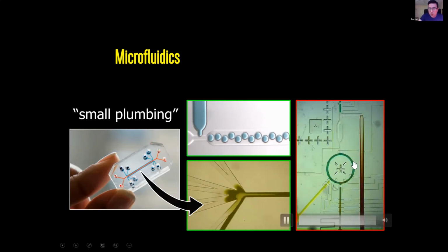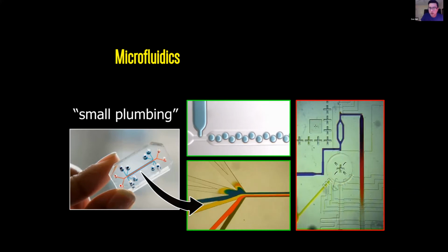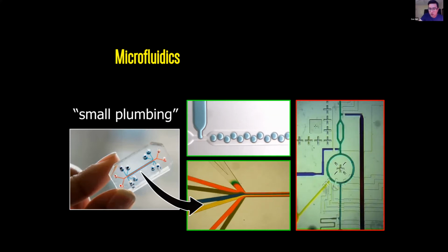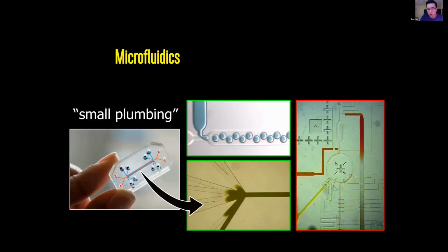Another example shown here in this movie is a multi-layered microfluidic device consisting of multiple layers. By using compressed air, you can valve and pump fluid flows in microfluidic devices for analyzing biological materials. This technique is called multi-layer soft lithography, developed by Steve Quake's lab at Stanford, and it became the basis for starting a company called Fluidigm, which sells gene sequencers and nucleic acid analytical platforms.